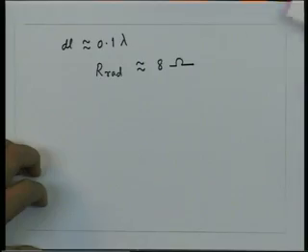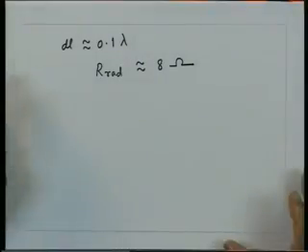So radiation resistance is a good concept when we try to estimate the power radiated by a given antenna. By devising a mechanism by which the radiation resistance can be increased, we can radiate more power for a given excitation current in the antenna. Having done this calculation for the power radiated by the antenna, we can now go to the directional characteristics of the antenna, and as I mentioned, this is captured by what is called the radiation pattern of the antenna.